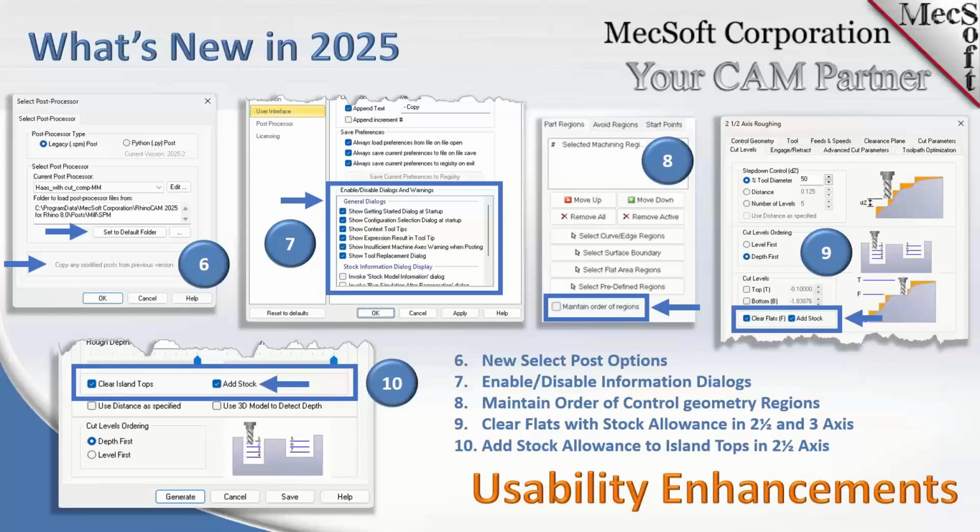Joe, you can jump in here and correct me if I'm wrong. Let me go ahead and explain this. So previously in profiling, let's say you selected a bunch of curves. There would be a lot of pre-processing that happens to those curves. What we typically do is we check for self-intersections. We check for endpoint matching curves. So if there are two curves that are endpoint matched, we actually merge them into one internally. And then if they have self-intersections, we attempt to remove those self-intersections so the toolpath methods will work correctly. So there's a lot of pre-processing that happens.